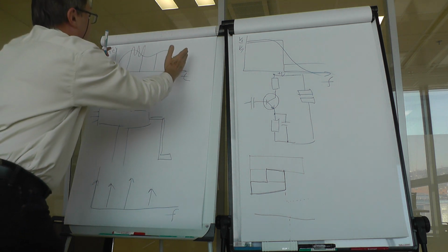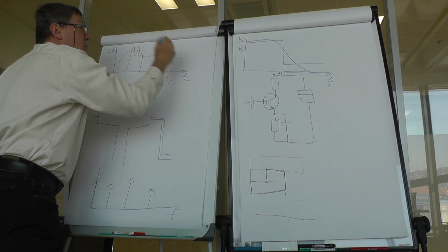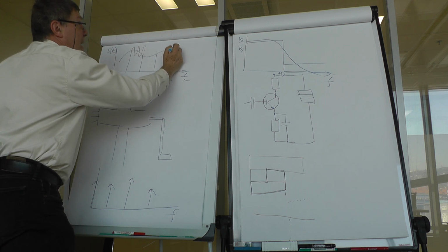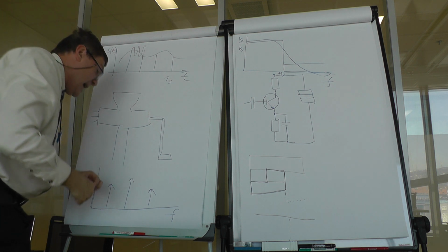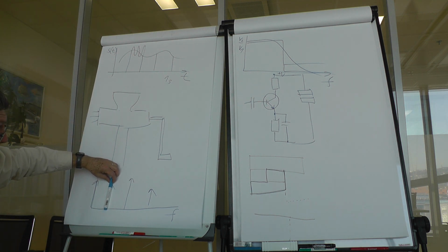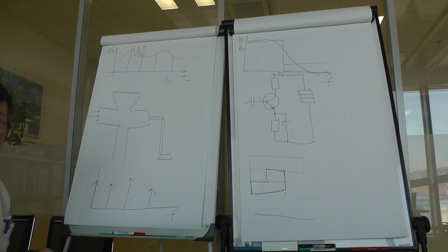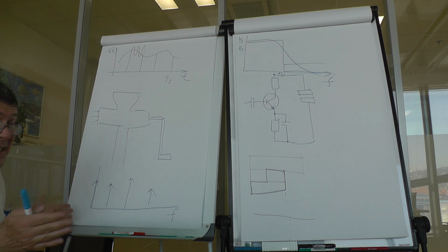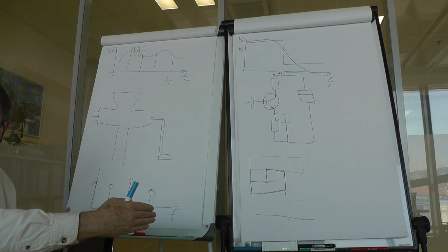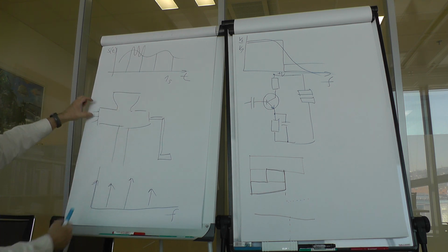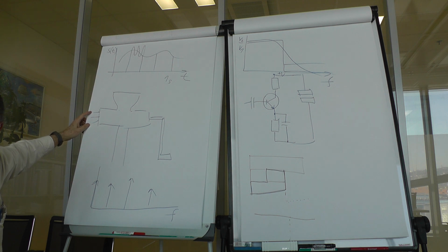In the case that the signal that I have sampled is periodic and I have exactly sampled one period of the signal, then I will get really the value of the first harmonic or the content of the first harmonic in the input signal. But what if I have some signal for which I do not know the period? So I will sample it for some time and then throw it to fast Fourier transform and get some frequency components.